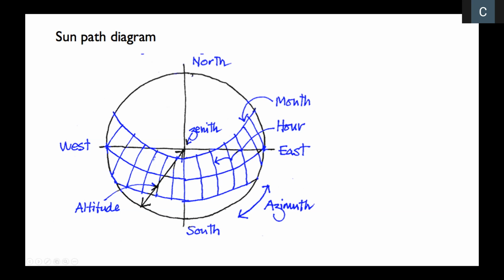And on your LOFSACs, those sun angle calculators, you have an altitude overlay, which simply divides this full distance into regular increments, such that if you were to go to this end of that line, you are at an altitude of 0, which is to say the angle measured from the horizon up towards that point that you're pointing at in the sky is 0. You're pointing at the horizon. And as that altitude increases, you gradually point higher and higher up until you are pointing directly overhead.